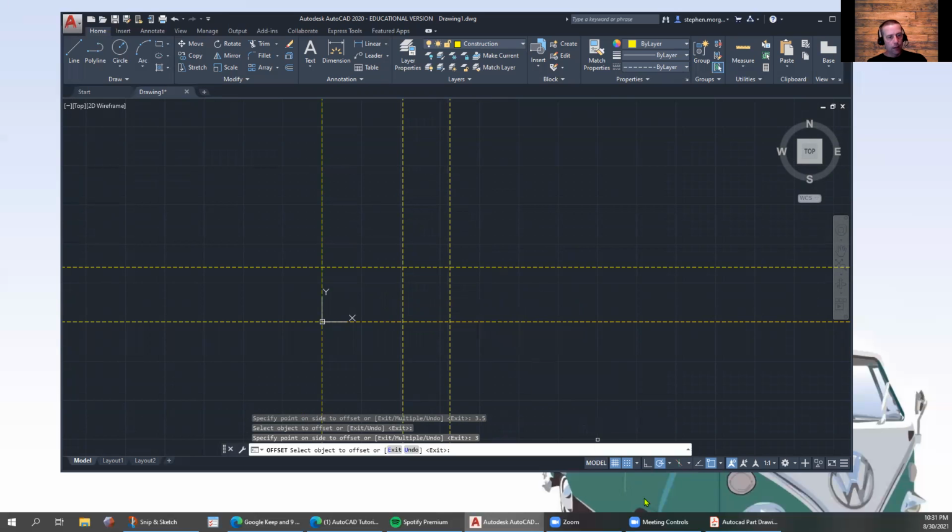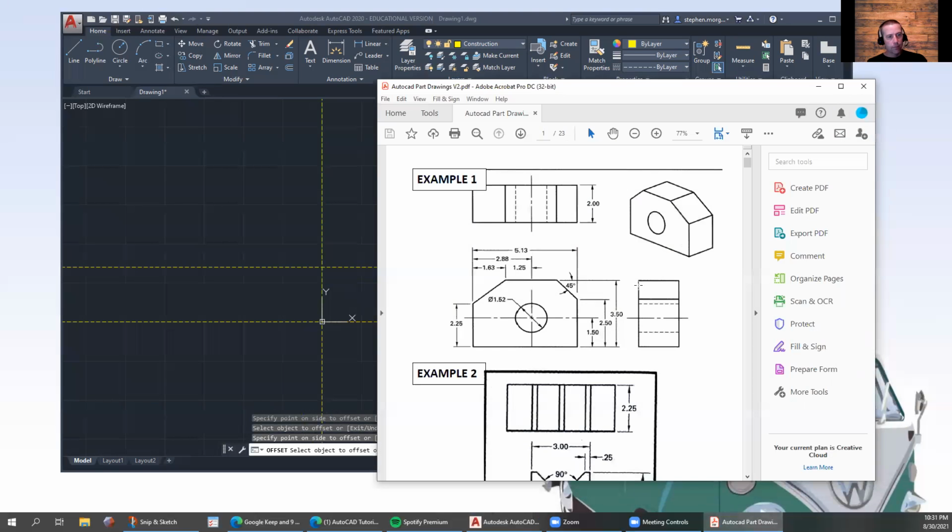And then let's consult our drawing again. Now we've got a line that borders here. We've got 3 inches here to our next line. And then we want to get another vertical line along this edge right here. This view doesn't give us this dimension, but if we look in the top view, there is our dimension.